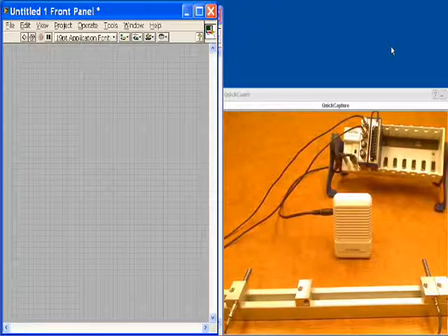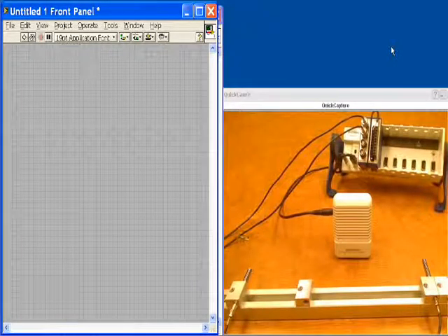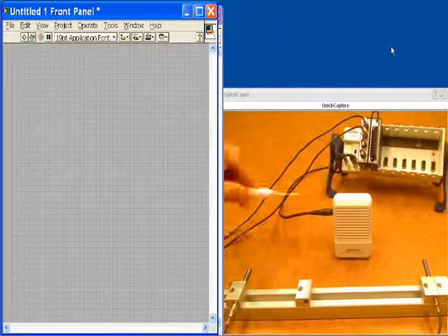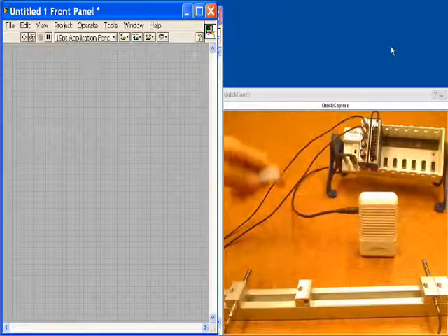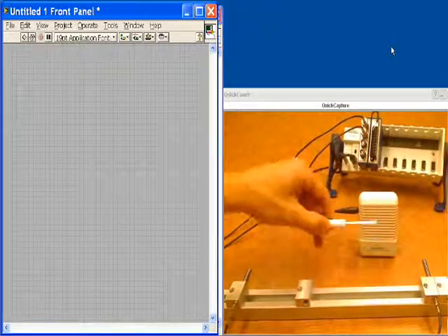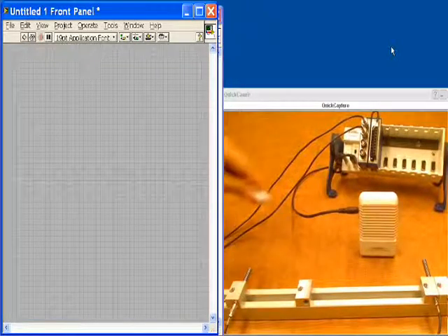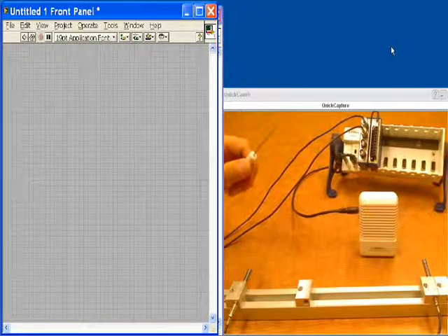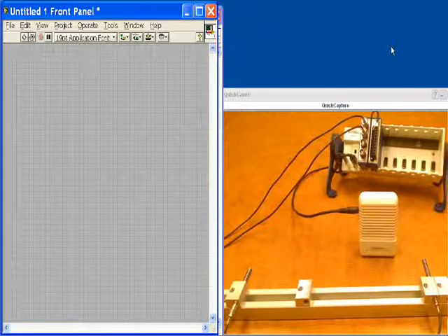What we're going to be doing is generating the sine tone and reading it into these two microphones. The time that it takes this sine tone to reach each microphone will be dependent on the position of the source itself. So in this case, where the source is closer to this microphone, this sine wave will reach here first. Then it will reach here later, and that delay will show up as a phase difference between those two signals. We're going to measure that phase, and then we'll be able to show you or point to the position of the signal source. So that's our setup.